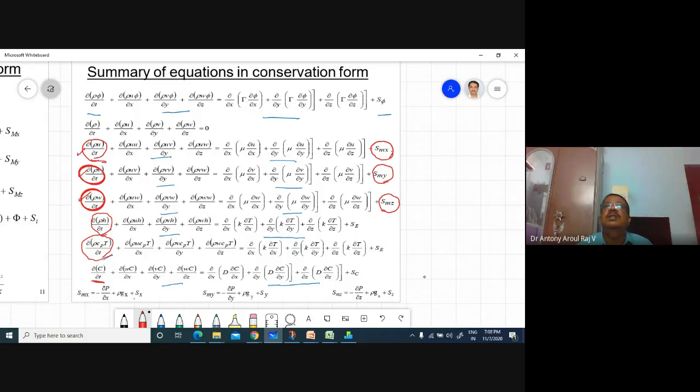So what you can do is, when you are modeling with CFD, you know what a fan will do: the fan will create a velocity in a particular direction. So you split that velocity into 3 components. Okay, so that means what? A fan will create a momentum in a particular direction. Am I correct? So the fluid will flow with some momentum in a particular direction.